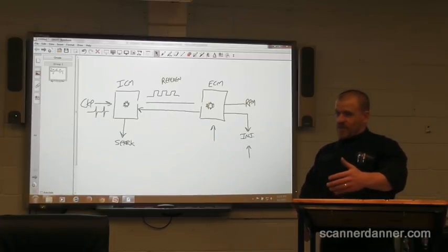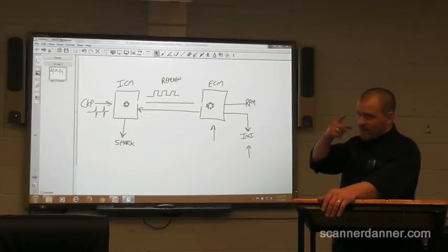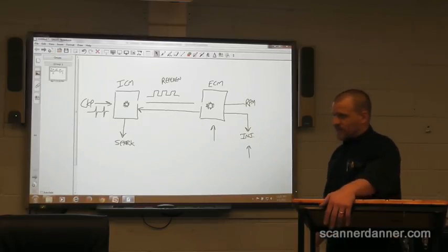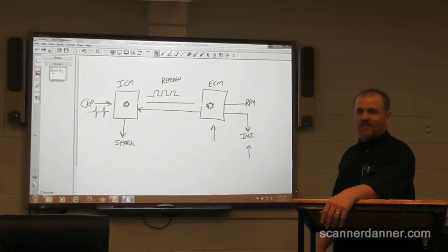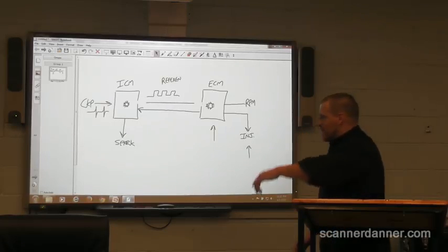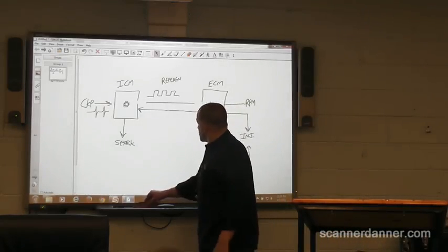I know some of you might be thinking, but wait, your test light didn't light. You're right, it didn't light, so we can't have a short to ground. That is incorrect. We could have a partial short to ground. That would be not enough to light the test light, but enough to pull that signal down. Let's do the test and I'll expand on that.